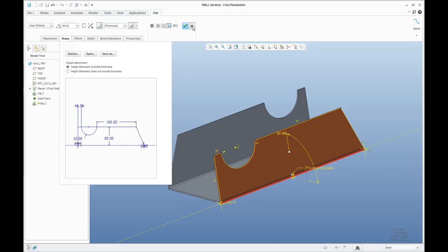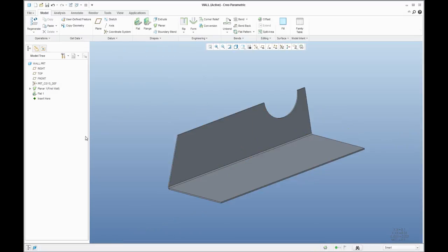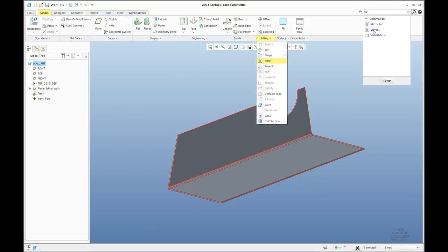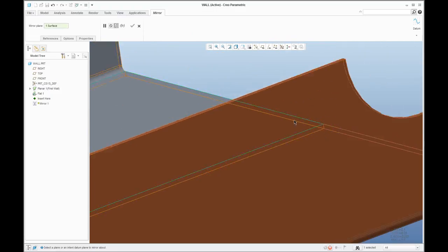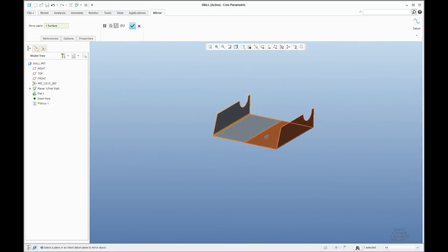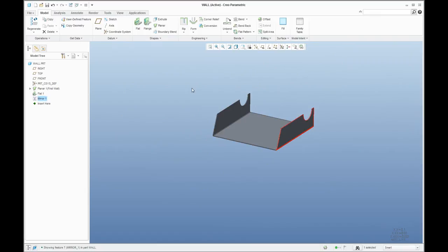Okay. Or you can really easily select the whole 3D model and directly select the mirror feature. If you don't know where it is placed, you can use the search functionality and the system automatically shows you where the mirror feature is placed directly in the Sheetmetal. So I'll select the datum plane or 3D surface, and it's fine.